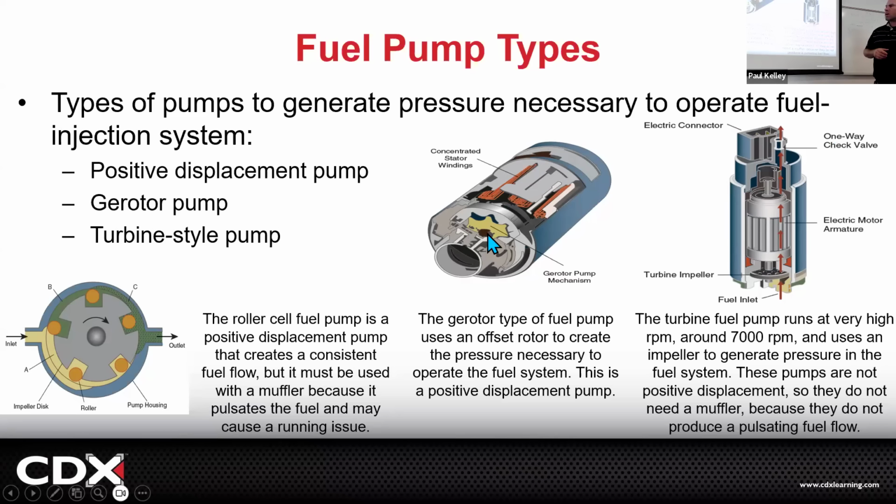What if you have mechanical wear on the pump and it's bleeding pressure internally and it's not able to put out all the fuel it sucks in? You think that's going to have an effect on your fuel pressure? Yeah, so it could be the electrical part or it could be the mechanical part.